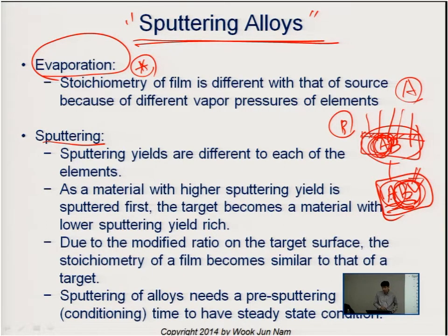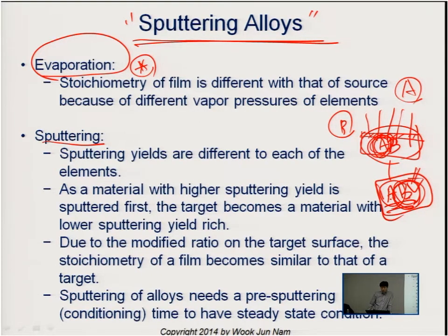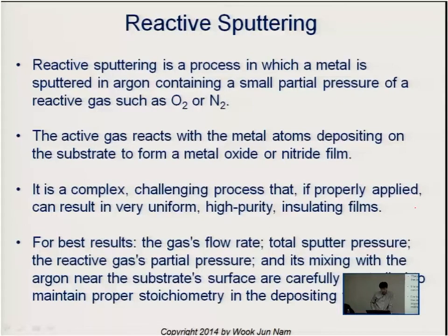Without doing anything, without using any separate power supply, sputtering can deposit a compound with much closer stoichiometry. That's one of the advantages of sputtering over evaporation.